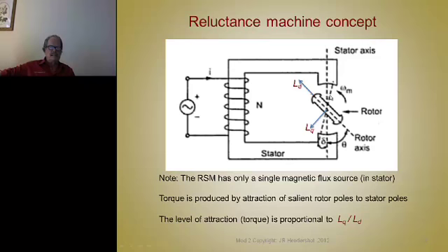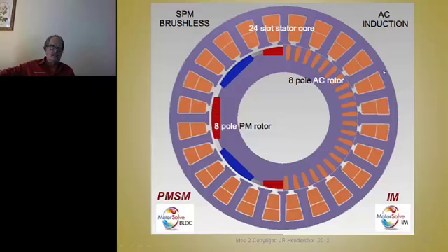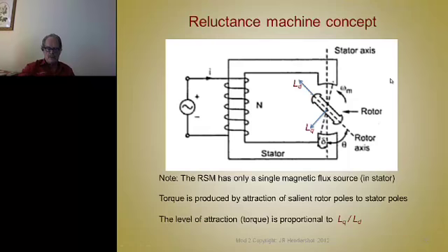Now, if we take that same piece and rotate it on the shaft so the rotor goes this way, we've got lots of air in the circuit. And we measure the inductance on the coil. Now the inductance is the quadrature axis, because it's 90 degrees from where it was on the direct axis. So you measure the inductance of the circuit when this arrow is pointing, when it's vertical like that. Whoops, I went too quick. Then you have a very low inductance.